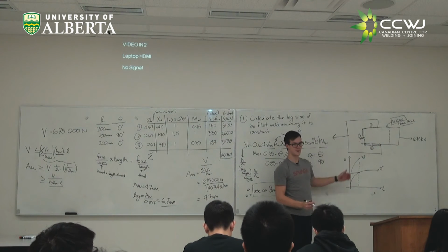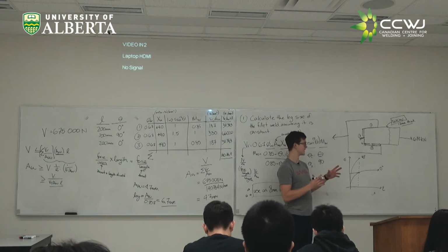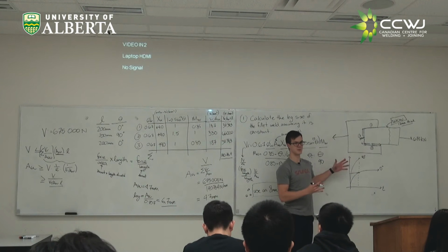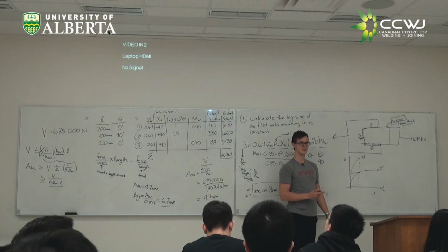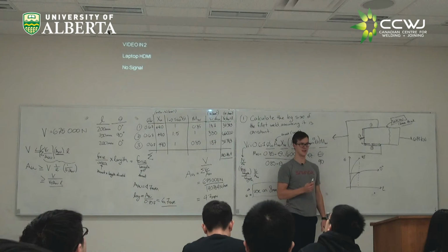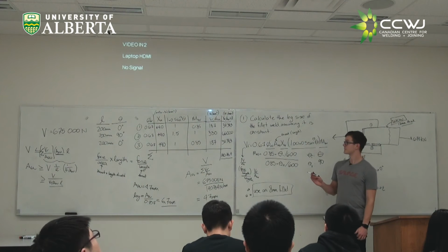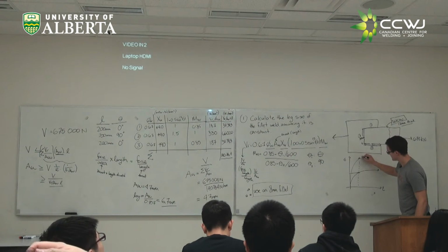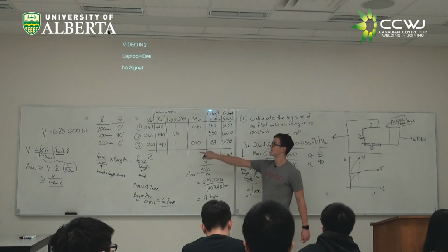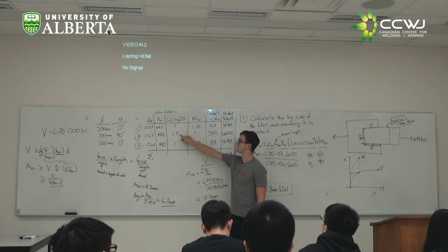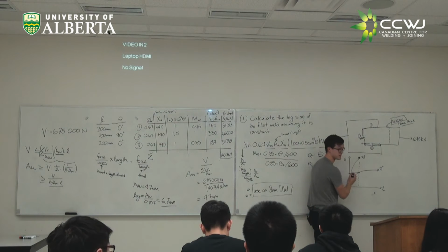So despite the fact that all of our welds are the same length, because this one is going to act more rigid, this actually can handle more stress at the point it fails than this can handle at the point where this weld fails. Are those 2 points represented by that? The difference between this point and this point is represented by this first factor here, where this is 1.5 and this is 1. That's because this is roughly 1.5 times this.